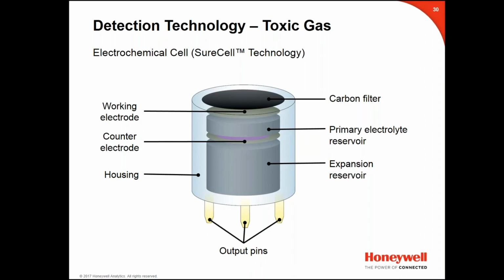So when it comes to portable gas detection, it's all going to be dependent upon the hazard. Typical first responders, as a minimum, are going to use what's considered a classic 4-gas detector. It's going to be combustible, oxygen deficiency, carbon monoxide, and one other gas. It could be hydrogen sulfide, it could be ammonia, but typically a 4-gas monitor is generally used, and that's typical throughout the industry for portable gas. That fourth gas is somewhat selectable, right? Yes, it is. In the oil and gas industry, it's generally hydrogen sulfide.